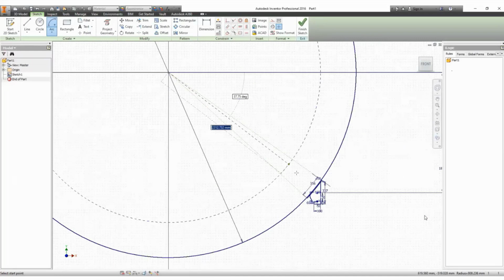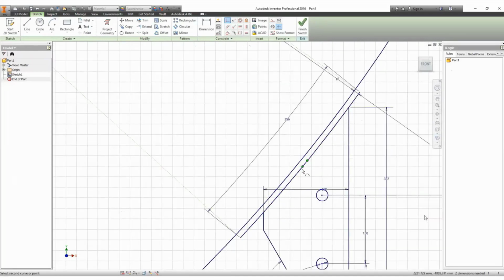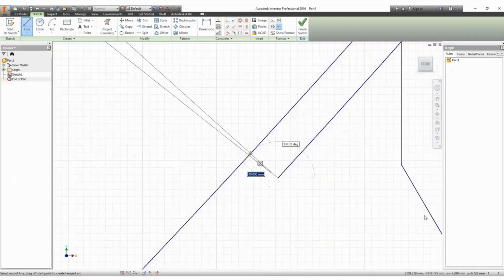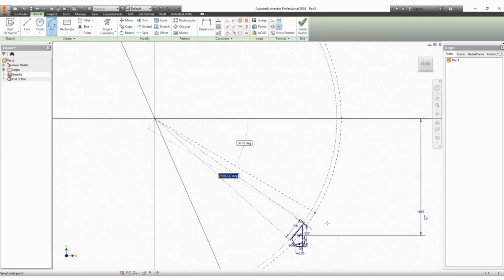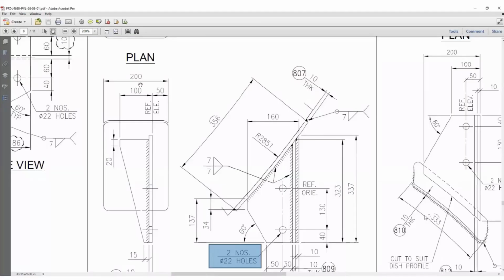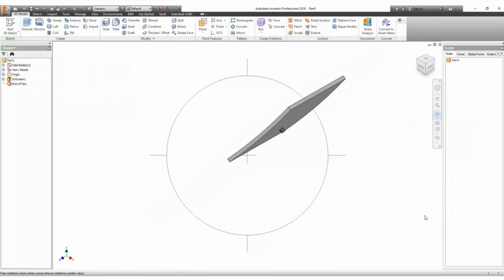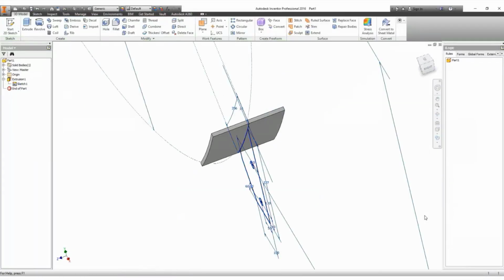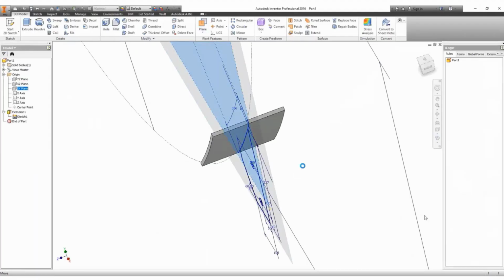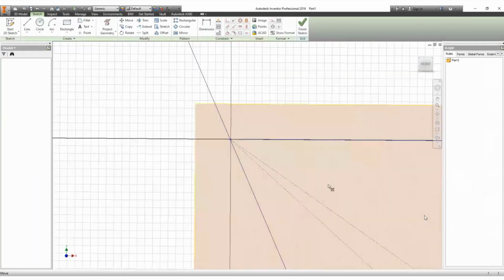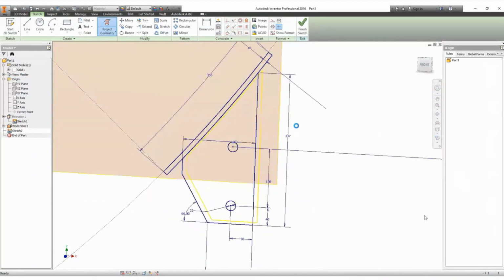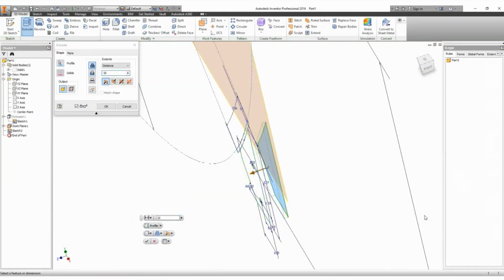Okay, and by making some modifications on the 2D sketch, like closing the sketches to identify the area of the wear plate by adding arcs and lines. Now we have this sketch, and we will create the wear plate for this part. Here we have this wear plate, and now let's add the stiffening clip or the clip. So let's make a work plane with a defined location. And let's make an extrude, give it a thickness.